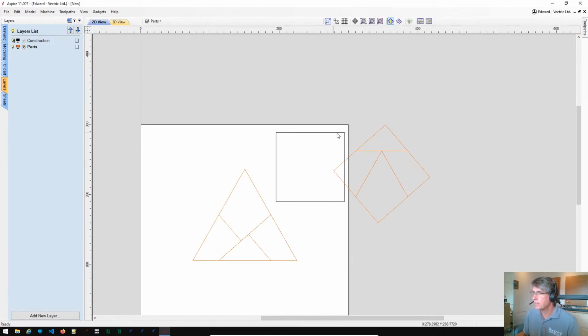And in fact, I've locked that layer now, so I can't take a copy of it. Let's unlock that. If we take this rectangle and drop it in there and change the rotation center to be that corner. So if I click the middle, I get the rotation center, click that, and drag it up to the top corner. Now that we can rotate around that point, you should see that we have got, within our tolerance, a rectangle, or a square now, that will be 98.7 millimeters square. So that looks plausible, right?